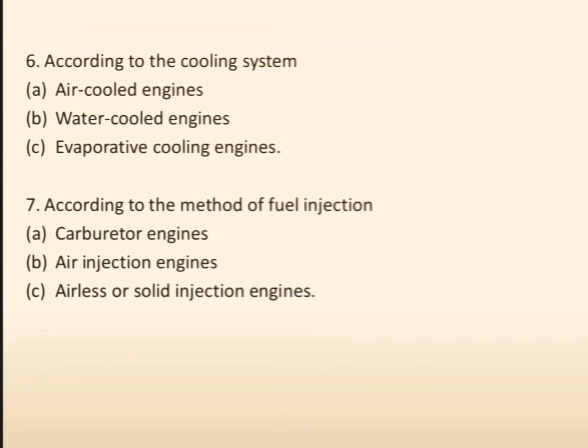Now another classification is fuel injection system based. First one is carburetor injection. In carburetor injection systems, a carburetor is used, a device used to prepare the charge, that is the mixture of air and fuel, to supply into the combustion chamber. And another one is air injection engines. See, in air injection engines, it's the control strategy in which fresh air is injected into the exhaust system for the secondary combustion of the exhaust gases.